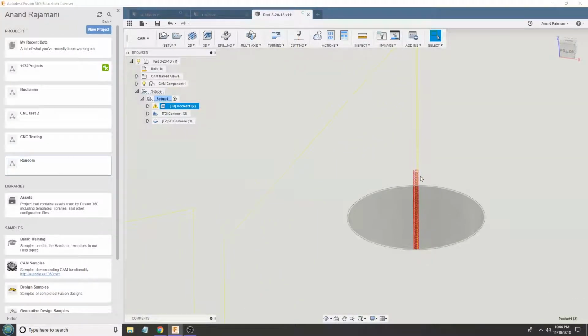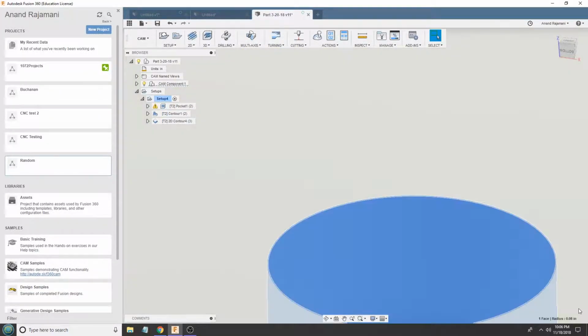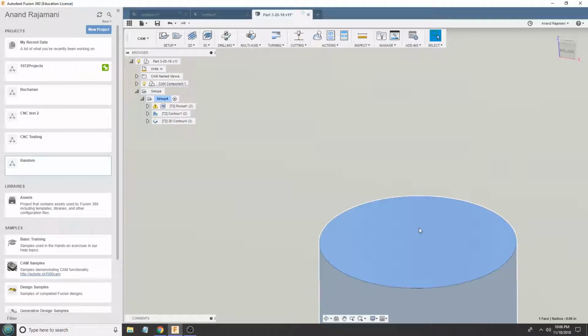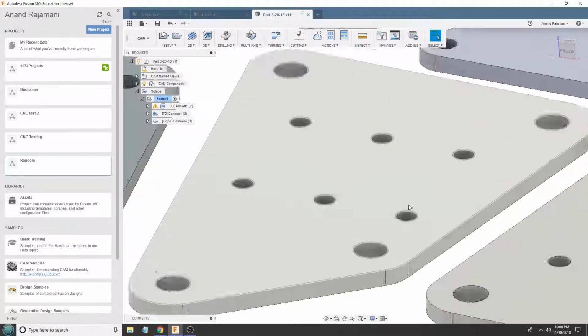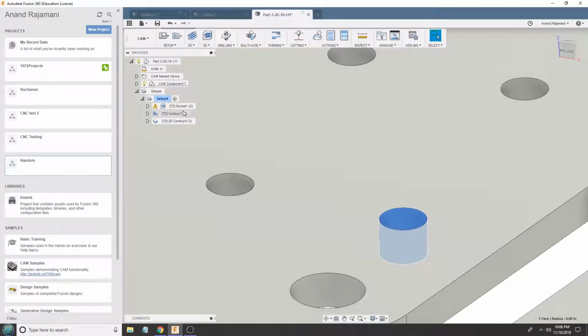And you'll notice for these, I got a very, very tight spiral because this is the 0.159 hole, and I'm going to be machining it with a 0.157 end mill. Really, 0.152 or 0.153 is what I have it in Fusion, but it really is a 0.157 end mill. So this is a very tight spiral in order to get in there.